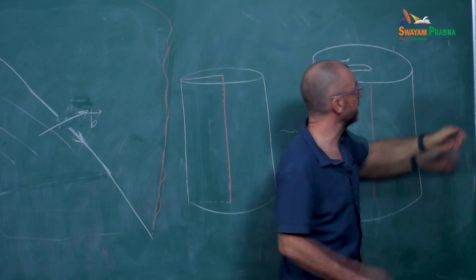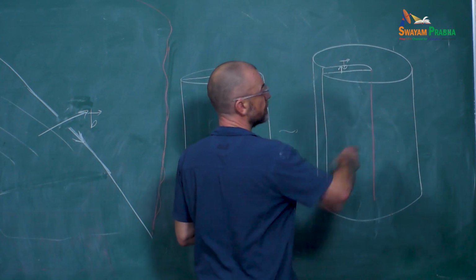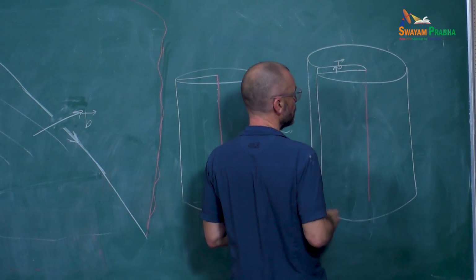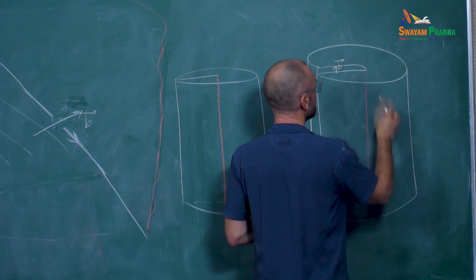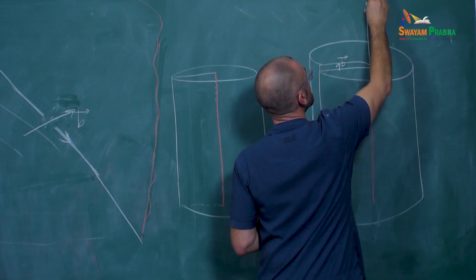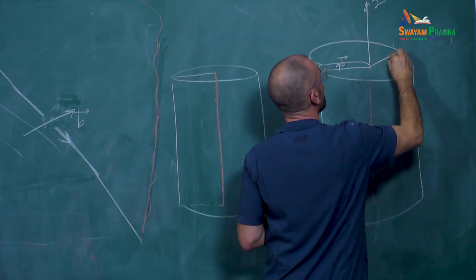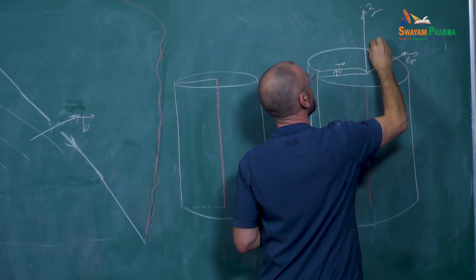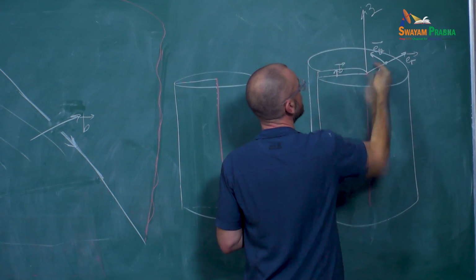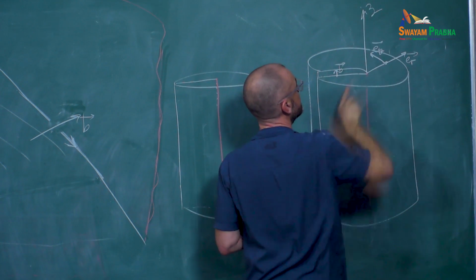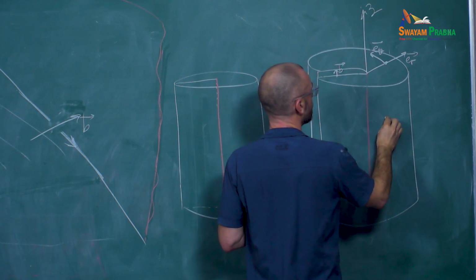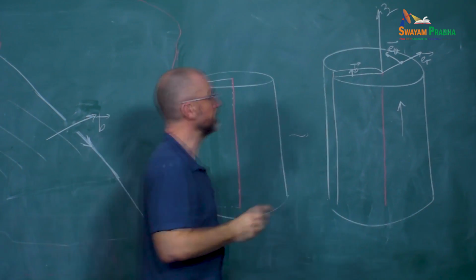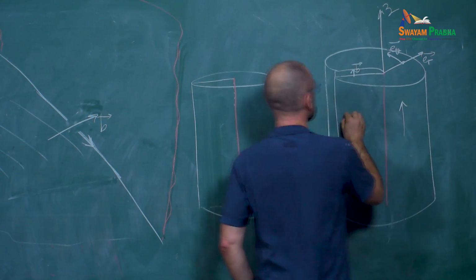And the simplest way to express the solution is by using cylindrical coordinates. And what you see in the solution is that you have displacements. So if I'm using, this would be Z, and then I have a cylindrical frame of reference. So I have an ER in this direction, E theta in that direction, EZ in that direction. The screw dislocation will create displacements only along Z. There's no other displacement.